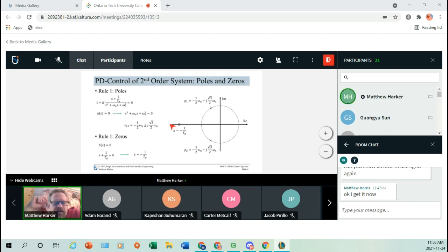So that's kind of what we'll end up with: you don't want to look too far ahead. That kind of reduced our stability. So basically now placing this 0 is going to be an important part of the controller design, right? So finding the TD and then the gain that gets us where we want to be.